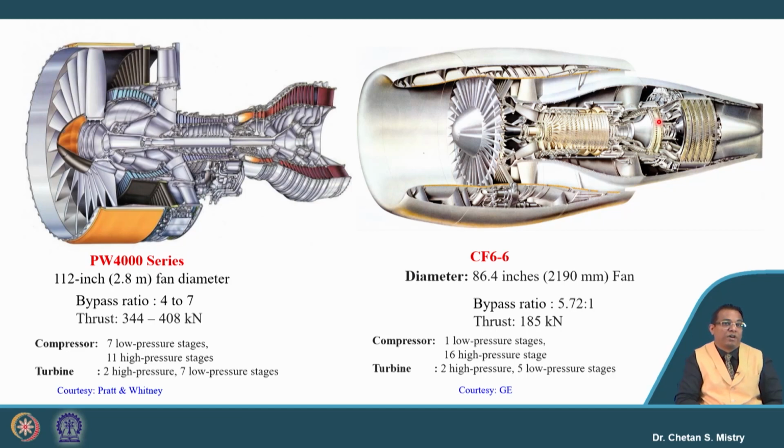Okay. Bypass ratio of 10, 12, 14, 15, you can move ahead, but that is creating trouble in fixing the engine on the aircraft. So, that also is asking for some kind of solution. Can we go with a very high bypass ratio? One more thing: suppose I keep this fan diameter the same, and in place of this bypass ratio being 7, I go with a bypass ratio of 10. What will happen? My core engine dimensions will be changing. Is it possible to go with that?